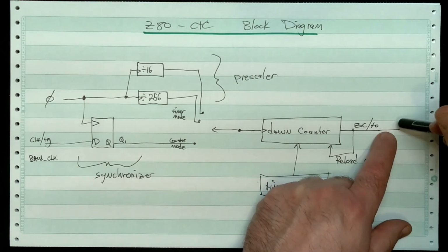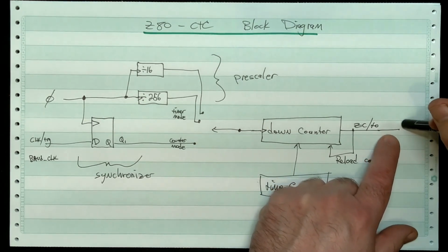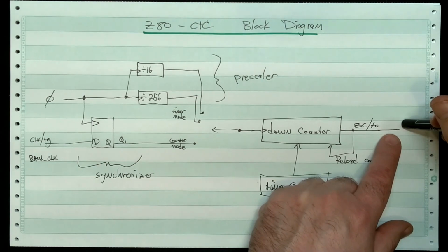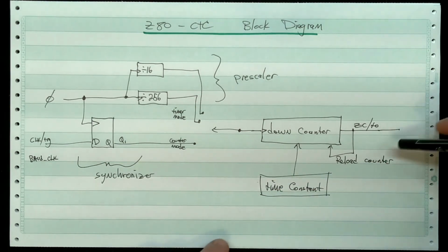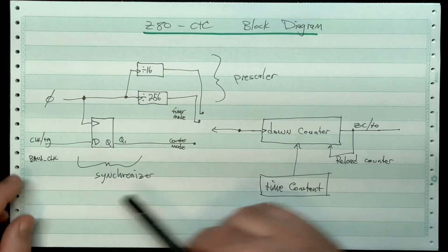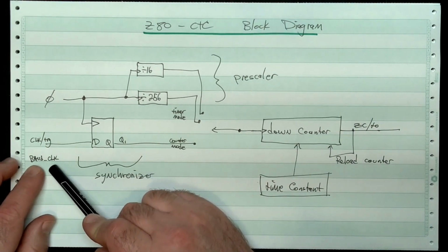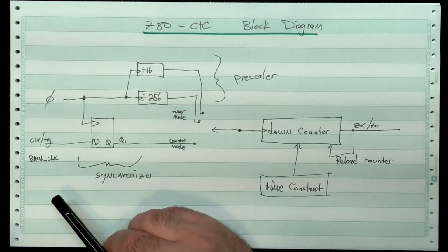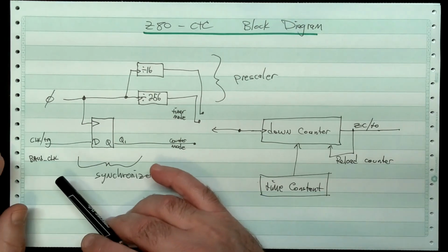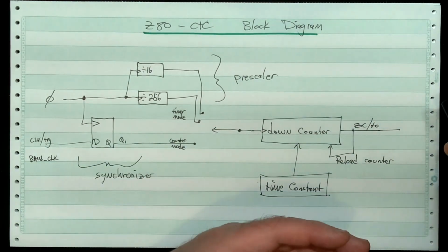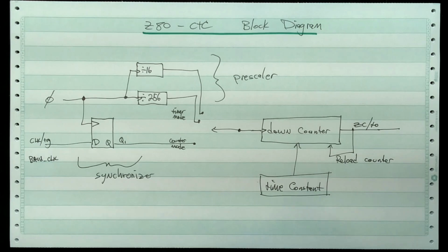So I would run it at 19,200 baud, which is a very common bit rate, okay, a baud rate. So this will divide evenly provided we choose the baud clock input. That's a nice clean multiple. Even though it's a weird value, it evenly divides these bit rates. That's why I chose that other crystal, okay?